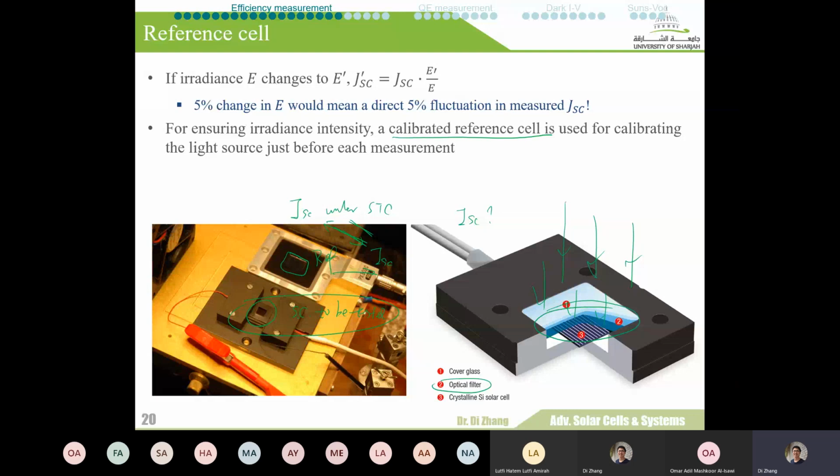So if you want to work on a specific solar cell with a specific range of wavelengths where you have a response, they will adjust the optical filter so that only this range of light goes through the reference cell, and your reference cell will only respond to this range. And if you do calibration within this range only, you will get the most precise results.